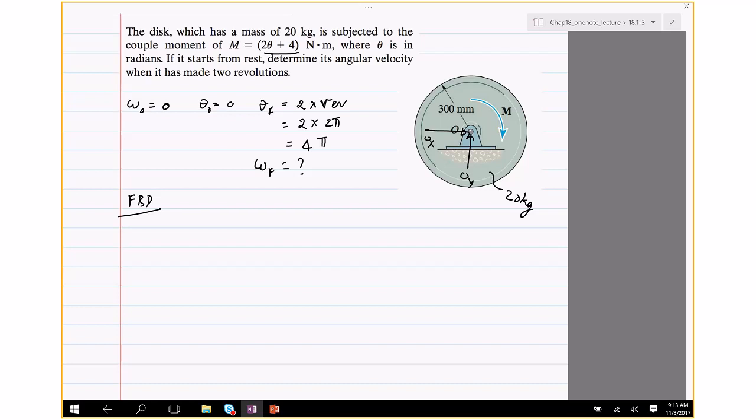A free body diagram is when you pull a body away from its constraints. In some cases you draw a free body diagram of multiple objects, but that's a free body diagram of the system. In this case, you have to pull this thing out and draw it separately like this, with OY and OX.